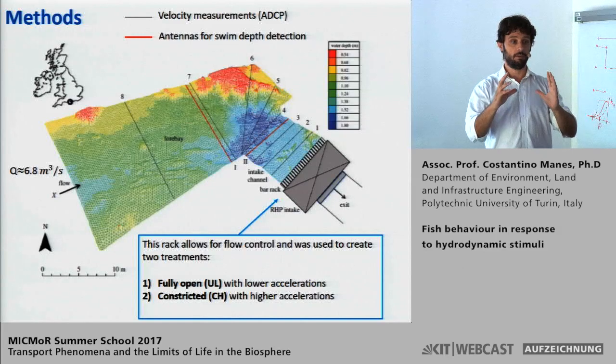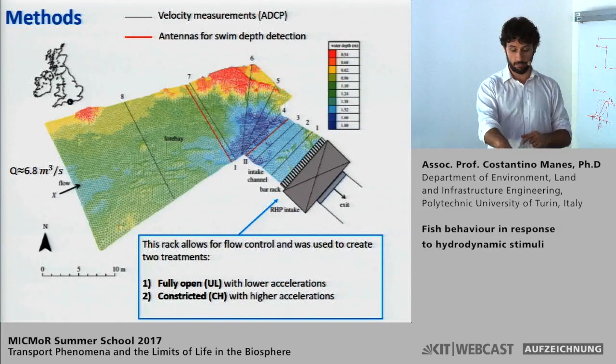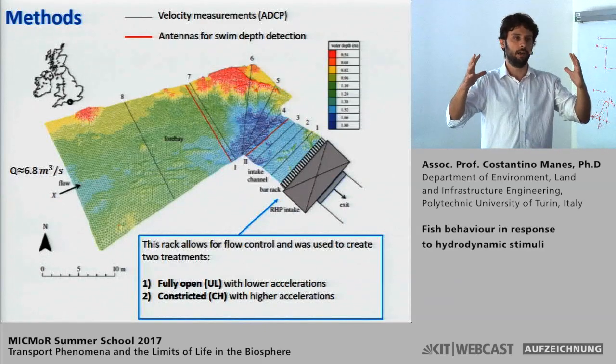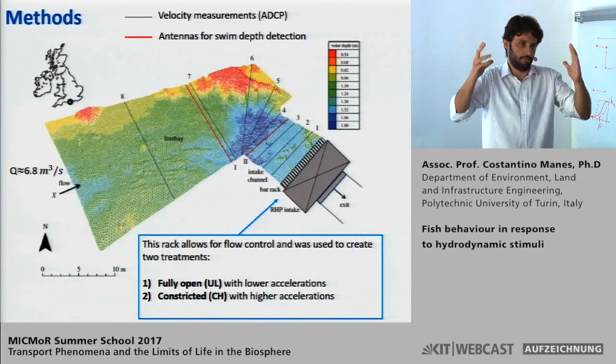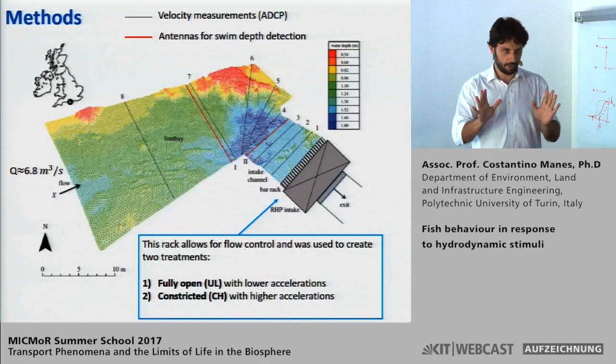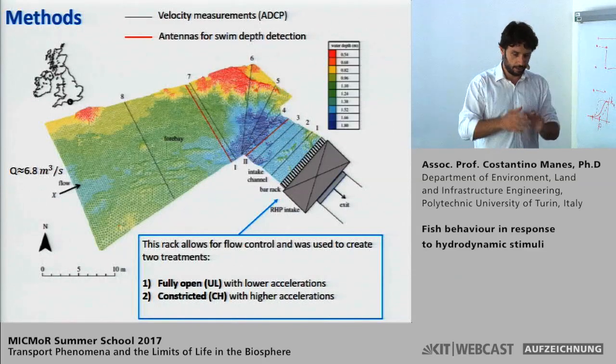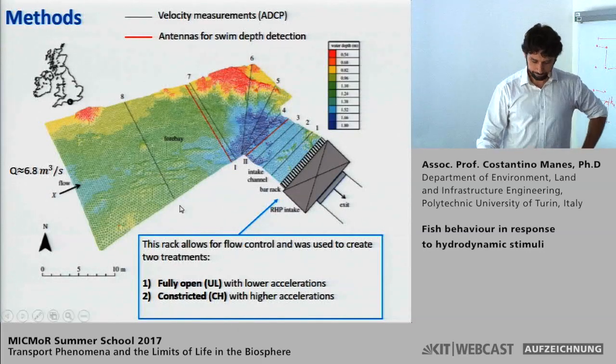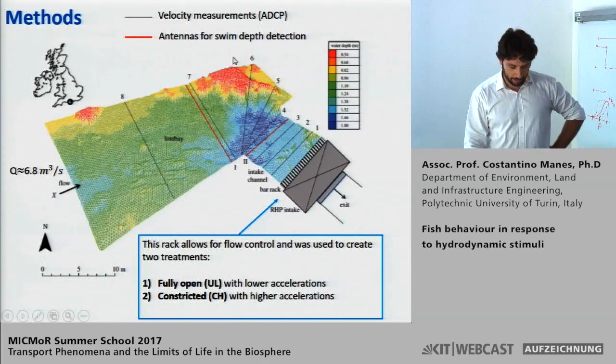So what that actually measures when flow depths are this shallow is the bulk, the mean velocity, the depth average velocity, nothing else. So nothing really fancy, no turbulence whatsoever. But we could at least map the flow fairly well.